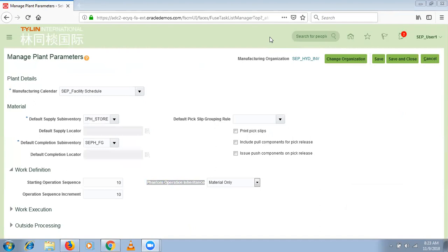So usually what will happen is that the wheel is going to have a separate structure, but we are not going to manufacture that wheel. If you want to manufacture that wheel, again we are going to maintain a separate structure. There are multiple levels of BOM. For this scenario also, we need to maintain another BOM. For that phantom, again we have to define a phantom build. So for this item, tube and tire are the components of the wheel.